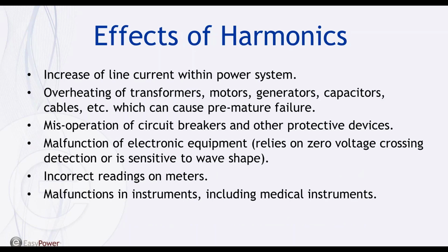So let's talk about the effects of harmonics. Harmonics can have detrimental effects on electrical equipment and power systems. Unwanted distortion can increase the current in power systems, which results in higher temperatures in neutral conductors and distribution transformers. Harmonics can also cause the overheating of transformers, motors, generators, capacitors, cables or conductors, etc., which can result in premature failure.